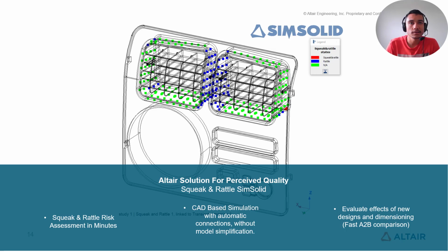instead of doing this back and forth process. So I do the FE analysis, it's not good, I go back to the CAD, improve the CAD, then I go again, generate a new mesh of this new product, and so on. So I can do a lot of iteration directly in the CAD, and then the model that goes to the next stage, the FE validation, is a way more robust design, all right?